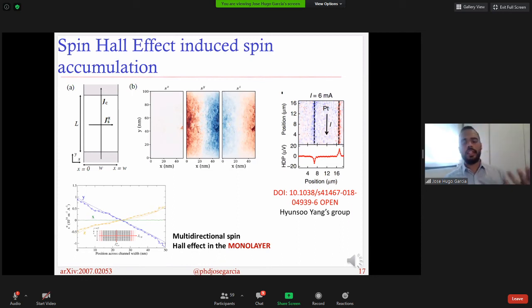What we did then was to try to determine the spin Hall effect. To do this, we created a two-terminal device, passed a current in one direction, and then measured the spin accumulation using Quant again. Looking at the spin accumulation, we saw that there is an accumulation in the y direction, an accumulation in the z direction, and zero accumulation in the x direction, as expected from the symmetries of the material, and in a similar way to what some people do through experiments.